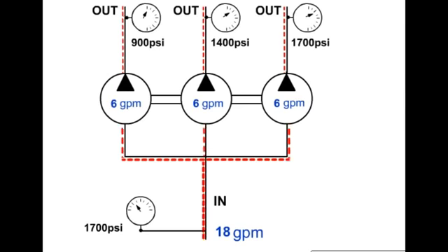The gear-type proportional divider can divide the flow into two or more flow paths. The positive displacement of the gear sections produces a constant division of the flow, even if the loads and pressures in the output circuits vary. The output flows are proportional to the input. As the input varies, the output flows will vary proportionally. If one of the output flows becomes blocked, all of the output flows will be blocked. Pressure intensifies in the circuit that is initially blocked.